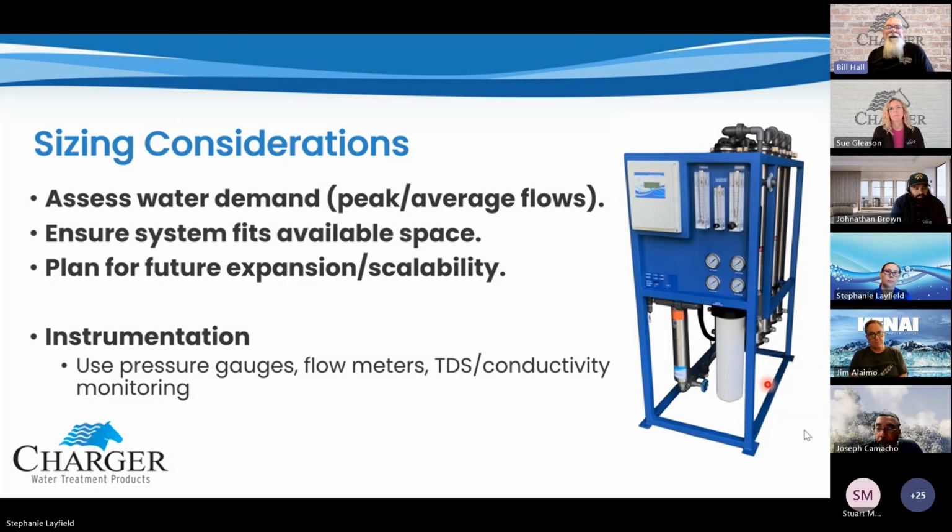Therefore, my rule of thumb, and this is strictly Bill's rule of thumb, on a 4x40 membrane would be figure 1 gallon per minute on your permeate flow. And that's just for sizing purposes. That gets you in the ballpark. Obviously, once you plug in your specific parameters and what your requirements are, you can dial that in.